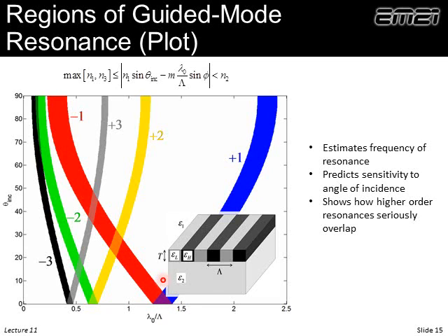What that means is the single resonance now splits, and we actually have two possibilities of where we could have resonance. And in fact, we'll see that as we come in at an angle, we'll have a single resonance for normal incidence, and then it begins to split as we come in at an angle. Now, if we like a nice, lone, isolated resonance, we could operate here, come in at a strong angle, operate on this particular diffracted mode, and then we're far away from these other resonances.